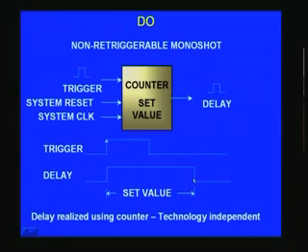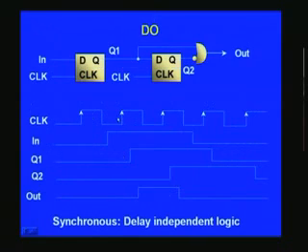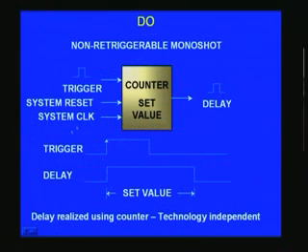Now you would notice, as in the previous case where a single pulse was produced, as well as in this particular example, it is technology independent. It is dependent only on the system clock. So you can see in the previous thing, this final delay is based just on the clock and not on the technology. So even if technology changes, any future technology that would come, your design investment that you have made, had you adopted one of the two schemes, is still preserved. That's how we say it is a technology independent design.